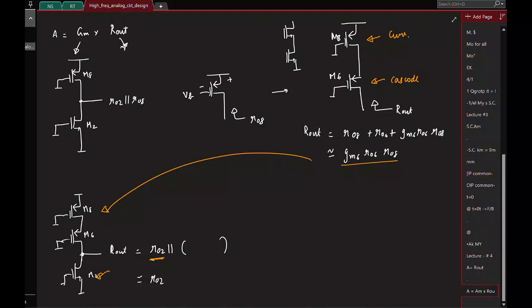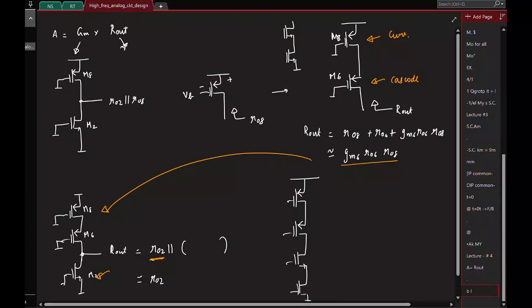We put a buffer down, same thing. We'll put a cascode for the NMOS also. That's all. So that gives rise to this. So this is say M2, M4, M6 and M8, and this is where I'll apply the input delta V. This is out.